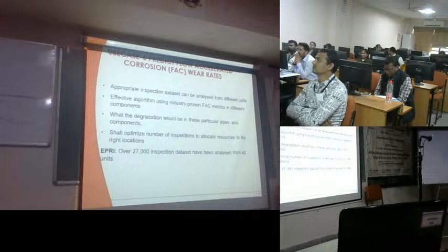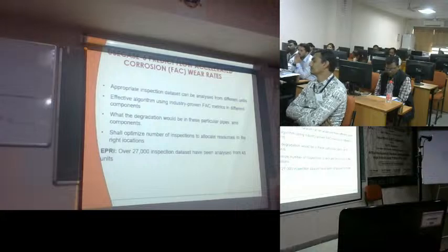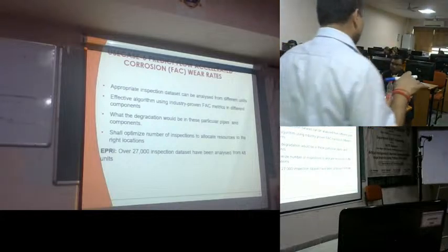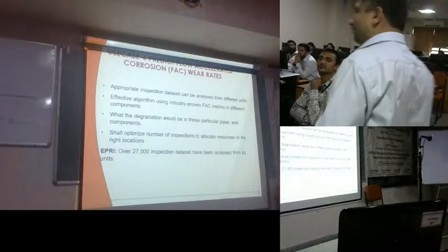So what this AI application does, starting from the origination, is keep recording the normal trend behavior of the metal, like the sound coming from the fluid flowing inside the metal wall. When corrosion occurs, the sound will change, and it keeps on monitoring many other properties. When we see a deviation in those parameters, it can know that corrosion has started and preventive action can be taken.